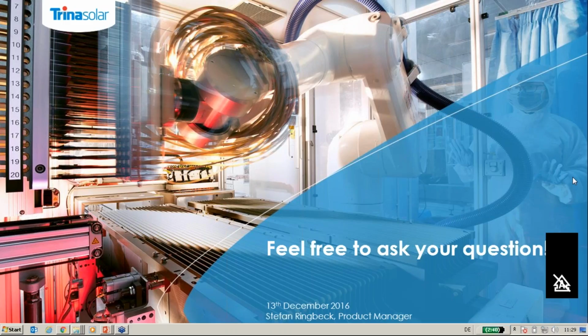So you have to take a look at the module technology you use, so let's say multicrystalline, monocrystalline, or mono with PERC technology, and then you can take a look at the complete system and decide on the system cost what is the best solution out of it. So should I go for a little bit more expensive module and then save on the balance of system, or should I go for, let's say, a multicrystalline, or a cheaper solution and then add more substructure, more combiner boxes? But this also depends if you have the space for it.